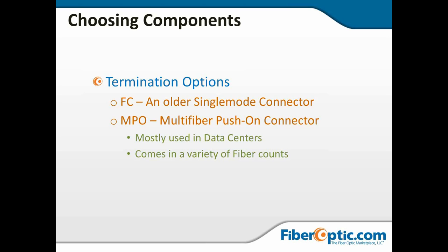We had some stuff in Barbados where we would plug an MPO on one side that would catch all 12 fibers, and then we could run those to individual receivers or individual transmitters, and obviously with the transmitters it would all be on a combiner. All of this running into the 12 fibers on a combiner, and then with the other end we would be receiving 12, sending it to receivers.